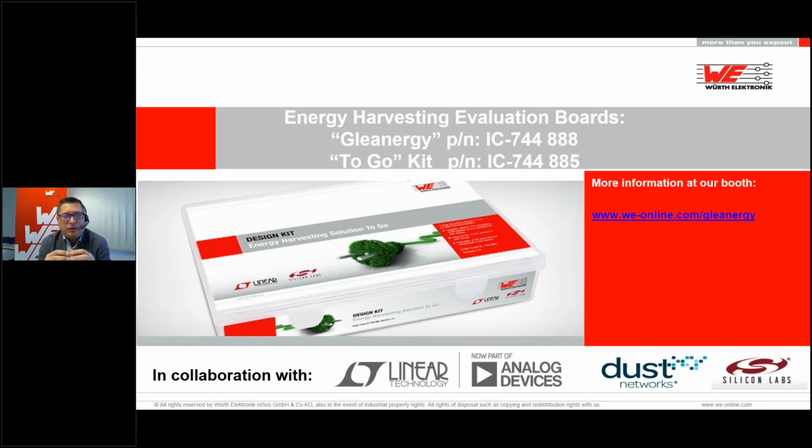So you have to look for a thermoelectric generator, because they are tuned to produce electricity, not to produce heat and cooling from electricity. So a 30 degrees Celsius difference is quite good. You can do good stuff with that. You have good voltage, and quite enough energy which you can grab with a small TEG. I don't like to say Peltier element, I like to say thermoelectric generator, and this effect is called the Seebeck effect. Peltier was the French guy, Seebeck was the German guy.